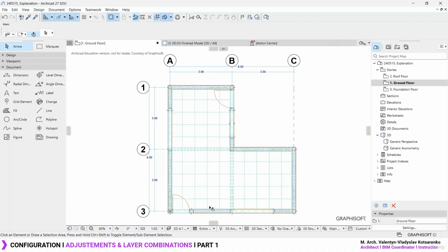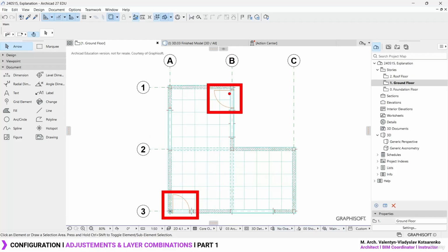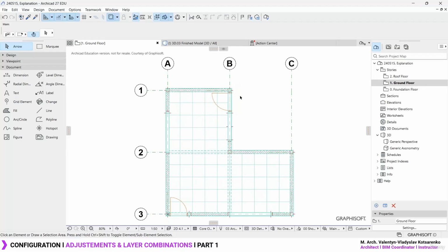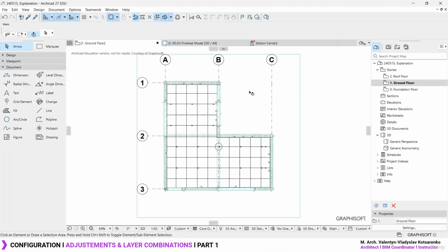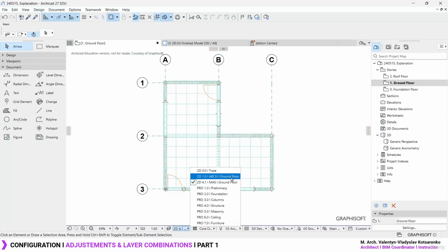We can even configure the preliminary just to visualize better the partial structure display. Instead of having the entire model, set it to core only. Yeah, we definitely still need to configure the correct model view options because we definitely want to deactivate doors and windows. But this is something we are going to fix in the upcoming lesson, so just give it a second. Just focus for now on having the correct definitions for your layer combination. Okay, so the dimensions are gone for some reason. I'm just going to once again dimension it manually. But as you can see, the layer combination is quite easy.